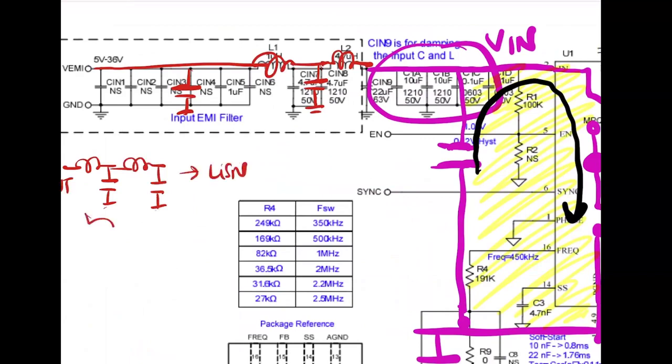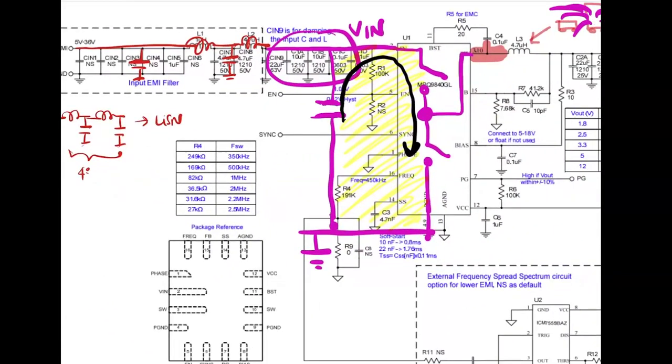If you use a 4th order filter, you will get several advantages. The first one is that for each component, you have 20 dB per decade of attenuation. But additionally, the inductors will be smaller in size. That means that they have less possibilities to pick up noise from the environment. And additionally, the size of the filter will be reduced and the filter is more effective.